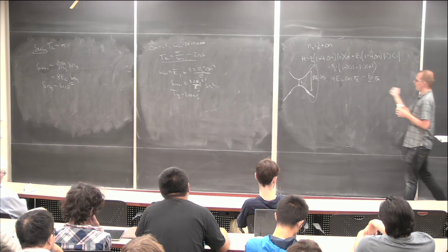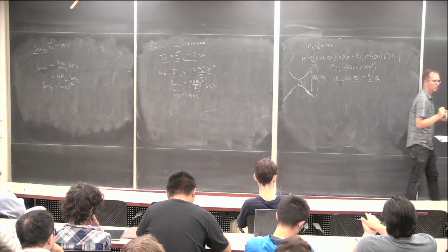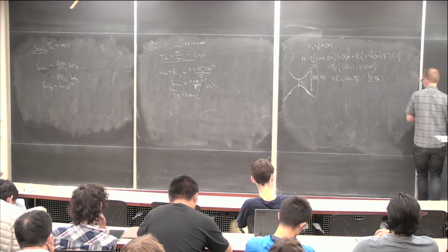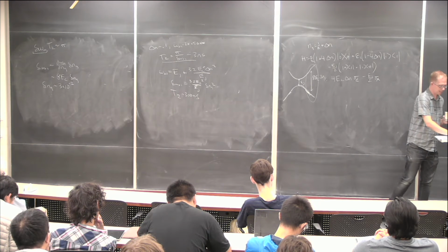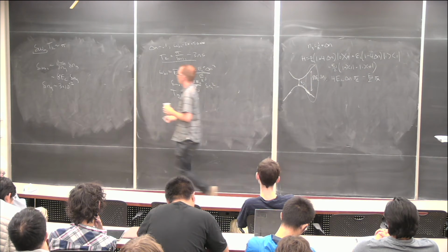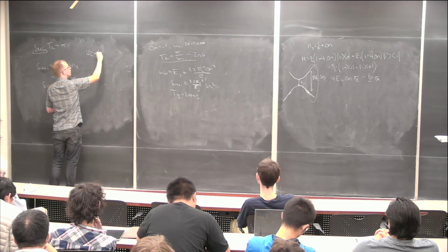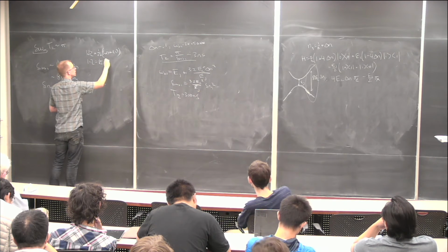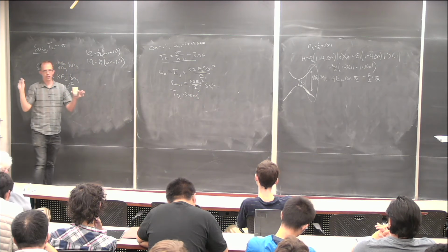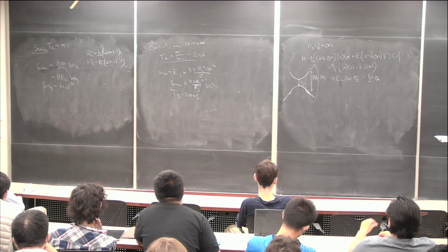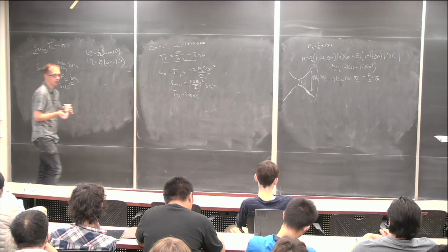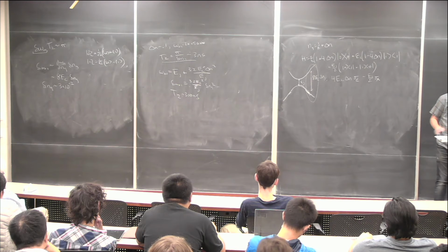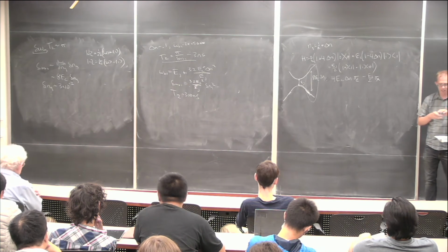And two, we said that we were going to measure this using a single electron transistor, which was going to measure the difference in charge between the 0 state and the 1 state. Well, now the difference in charge between the 0 state and the 1 state is nothing on average, right? So now our 0 logical state is equal to n equals 0 plus 1, and our 1 logical state is equal to n equals 0 minus 1. And so they have the same average charge. And so measuring charge no longer measures the qubit, and we don't have a tunable qubit. And so we've solved one problem of decoherence, but we've introduced 2 new problems of noise. Okay. So the first problem turns out to be not so hard to solve.